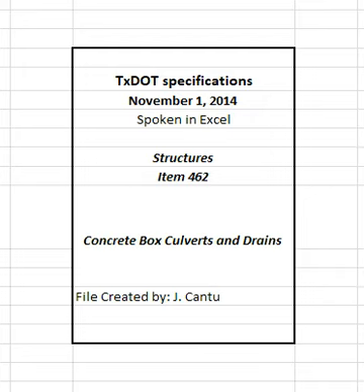3.4 Connections and stub ends. Make connections of boxes to existing boxes, pipes, drains, or drain appurtenances as shown on the plans. Mortar or concrete the bottom of existing structures if necessary to eliminate any drainage pockets created by the connections. Connect boxes to any required head walls, wing walls, safety end treatments or riprap, or other structures as shown on the plans or as directed. Repair any damage to the existing structure resulting from making the connections.